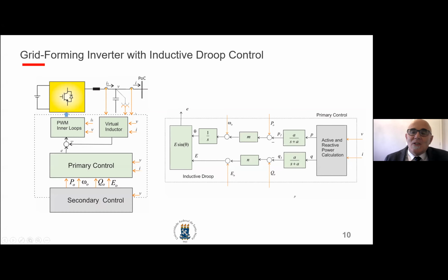Synchronous machines are known to be able to operate in parallel, since they have a large stator inductance, so basically you can parallel them, and they have this droop characteristic that is mimicked here somehow in the droop. The droop has been around for a long period of time.